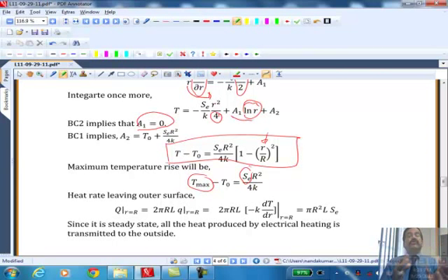So you want this to fail at a certain current capacity, or a certain value of S_E. What do you need to do? You need to find a metal that has a melting point low enough so that as soon as it reaches that maximum temperature, it will melt. That's how it breaks the circuit. So that's how you can find applications for simple equations like these.